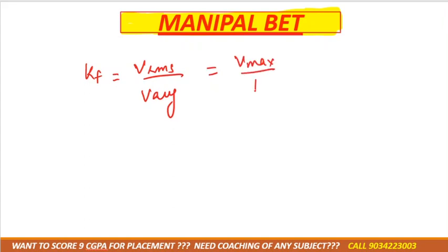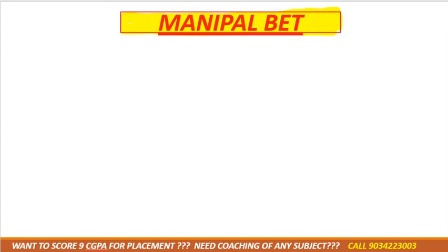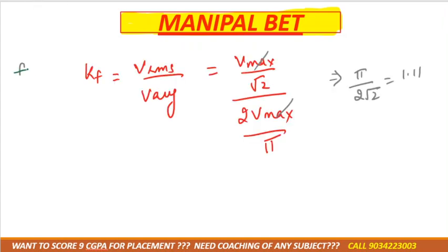Now form factor is, as I told you, VRMS divided by V average, and the formula for RMS is Vmax divided by root 2. Average formula is 2 Vmax divided by pi. If we solve it further, Vmax would be cancelled out. The final answer would be pi by 2 root 2, that would be 1.11. So always remember that form factor value is 1.11.